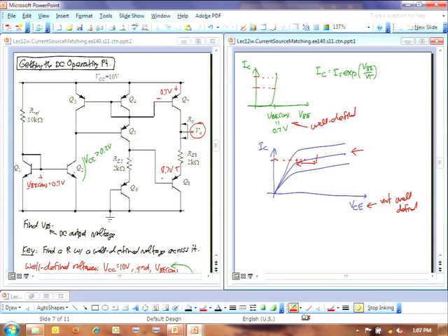Yes? How do you determine that one transistor out of all of that is in saturation? Well, you go through assuming everything's forward active, and then suddenly you find an inconsistency. Generally what's going to happen is you find all these transistors, then you find the voltage at that node, and you find that voltage is less than ground.